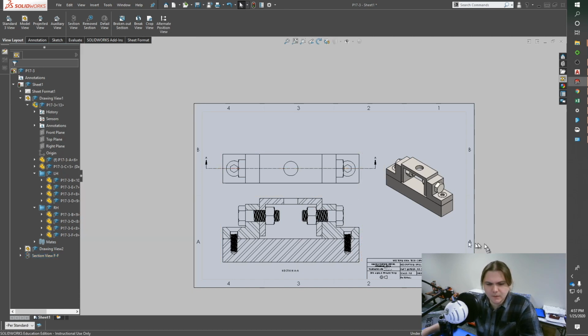and then check. Okay, so now there's no dimensioning that I need to do on this particular assembly. Everything kind of just fits together fairly obviously. So that will be the case on a lot of these that we do, that you don't really need dimensions, but there will be instances where dimensioning an assembly is necessary. So now I'm going to need a bill of material table and then the bill of material balloons, or BOM table or BOM balloons. So you'll hear me refer to that plenty.